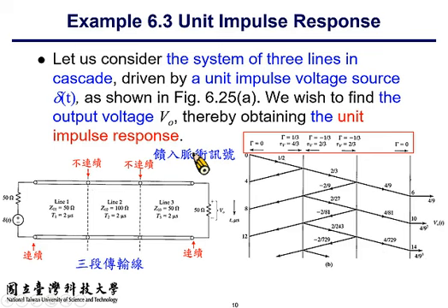And you can do the same for the second interface, looking from section 2 to section 3, with the corresponding characteristic impedances giving 150. So gamma is minus 1/3, tau is 2/3. And the reflection coefficient at the right hand, where you have a matched termination, is what?